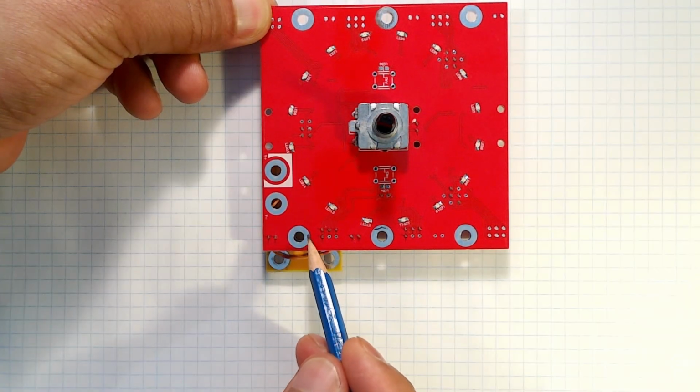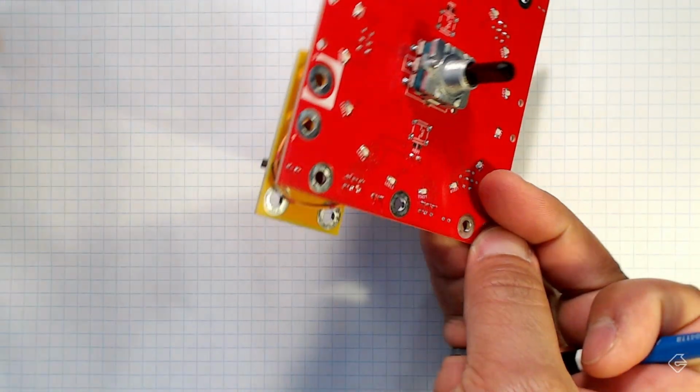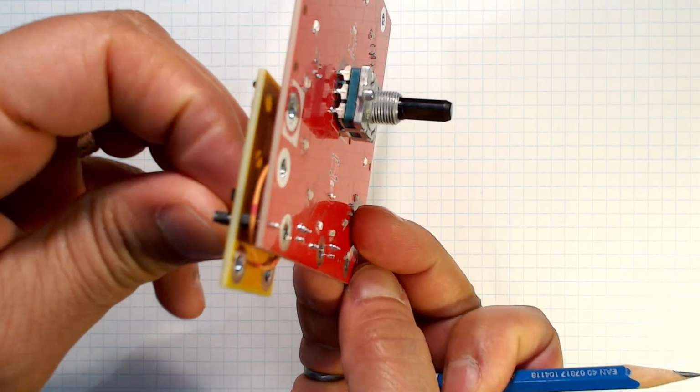This is going to be the hex pocket that's going to sit right on top of this terminal here, such that the thermal screw that goes in here will anchor to. Now, every time we've created a hex pocket, we've created a solid, then created a smaller solid, which is subtracted from that solid. We can use the same procedure here to create this hex pocket, but instead of doing that, what I'd like to do this time is create the solid that is the rim around this entire hex pocket. And by doing that, we actually don't need to subtract anything.